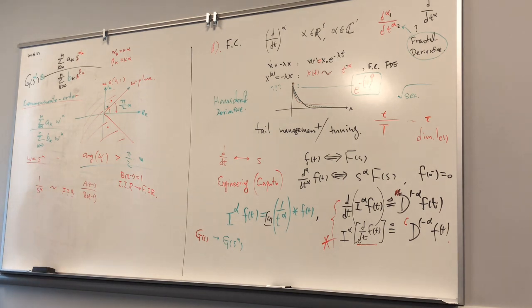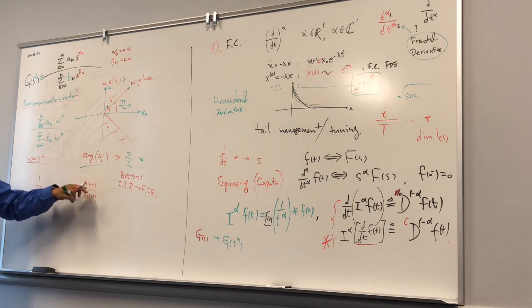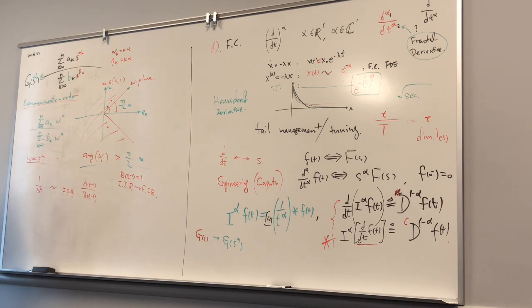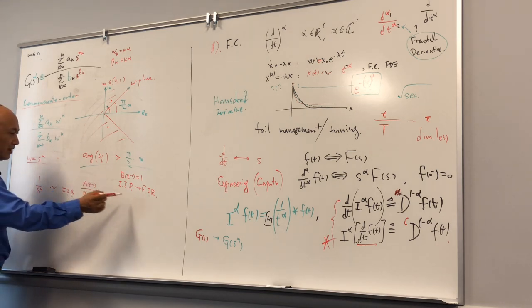A lot of people do FIR. I don't like FIR because with FIR you need a very long order to approximate this. While if you use IIR, you can have a smaller order of A and B combined and approximate this very well. So if you use the short memory principle and truncate using the Grunwald-Letnikov finite difference approximation, that will lead to FIR, okay?